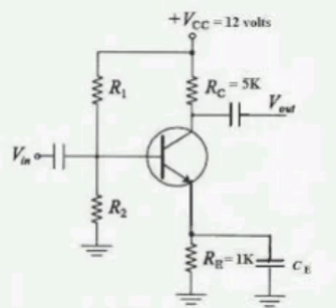Q chi s. Then p naught is approximately equal to Na equal to Ni into e power (Ei minus Ef) by kT. Ei minus Ef equal to kT natural log Na by Ni. Ei minus Ef equal to 0.026 electron volts into natural log 10 power 17 by 10 power 10. So Ei minus Ef equal to minus 0.419 electron volts.